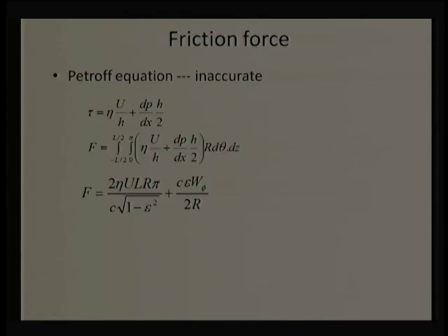Now, we discussed the load carrying capacity. We can use the short bearing approximation to find that out. In addition, I mentioned the bearing length should not be extended because that is going to increase the friction force. The question comes, how? That is what we are trying to find out, how to derive the friction force.